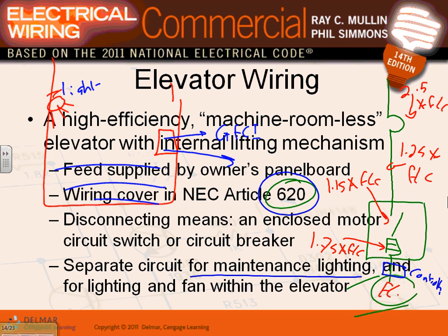Inside the pit of the elevator, depending on what type of elevator, you have to provide a GFCI receptacle for maintenance, to maintain the equipment at the bottom of the elevator. Maybe we should take you guys to look at the elevator that we newly installed. You can see the GFCI receptacle. Why do you think a receptacle is there? Maintenance. Why do you think a light is there? You're going to be maintaining what? Are you going to be able to see? So they have a light there.